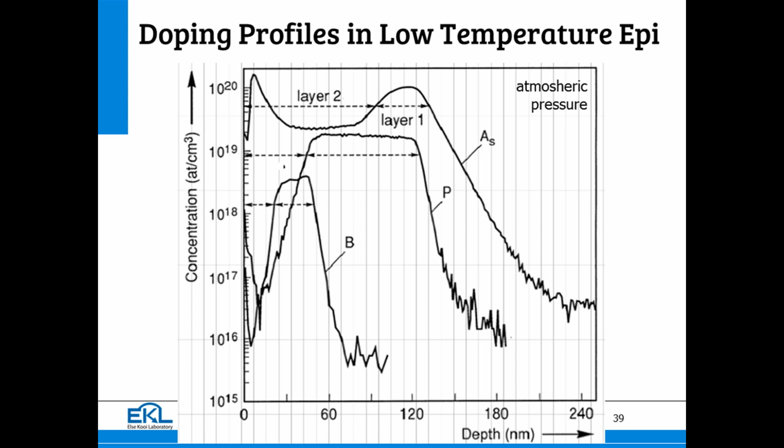The dopant transition is so sharp that there is no SIMS that can resolve the slope here. The same is true for silicon, the same is true for carbon. Extremely steep transitions. So the auto doping that we used to suffer from is totally gone.